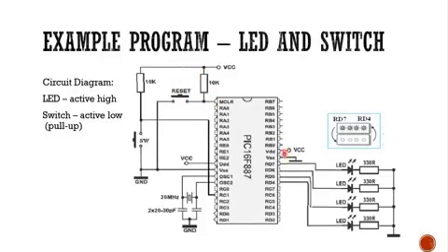Other than that, the IC must have its own 5-volt supply, positive, and then the other one will be the clock circuit. Right now the frequency that you want to use is 20 megahertz. So the capacitor range would be around 20 to 30 picofarad, both values. This one 20 to 30, this one 20 to 30. It can be 25, 25, or 30, 30. The values must be similar.